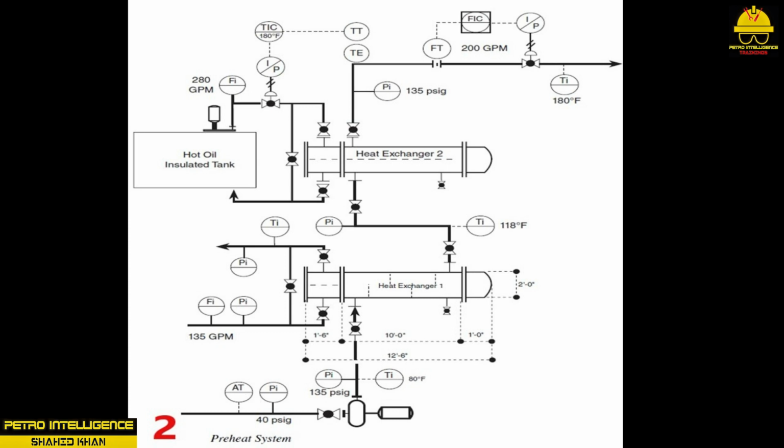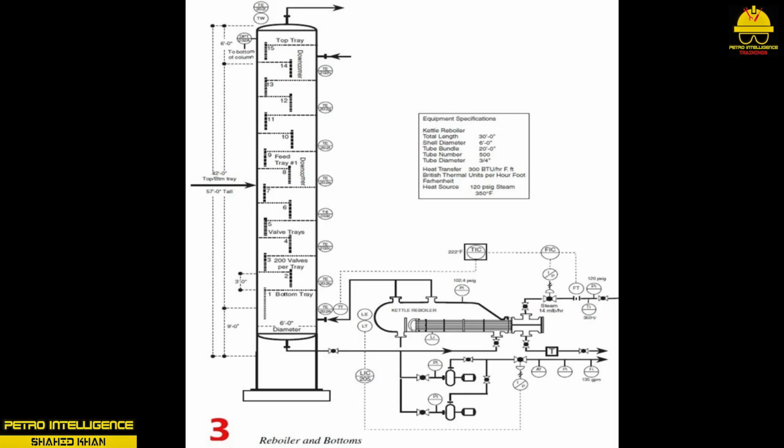9. Set unit feed FIC to required set point. Most units will increase feed in 50 GPM increments. 10. Set hot oil TIC to required set point. Monitor hot oil flow rate and temperature trends. 11. Set kettle Reboiler to 50% and put in auto. 12. Line up kettle Reboiler bottoms pump to tank farm. Check valve lineup. 13. Set kettle Reboiler TIC to required set point, auto.